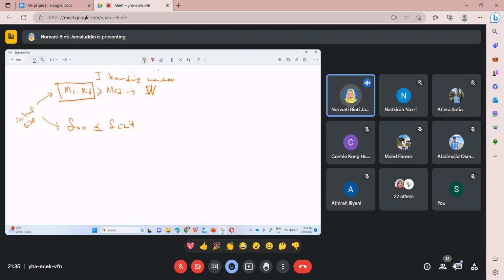Based on deflection, the unknown will be I. Based on this, refer to blue book and choose W or I that's slightly bigger than the required value. You get W required, I required. From blue book, you provide W provided or I provided that's slightly bigger than the required.